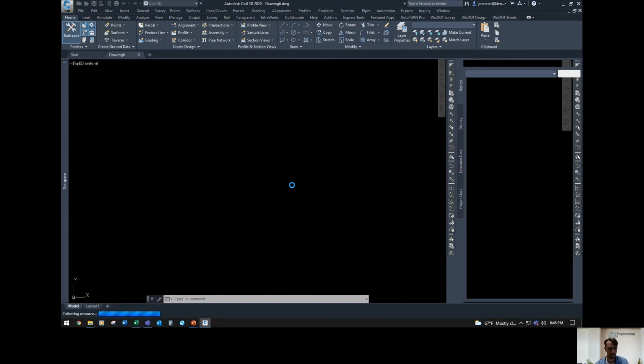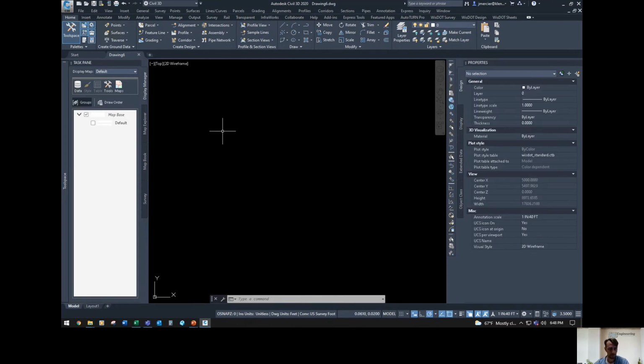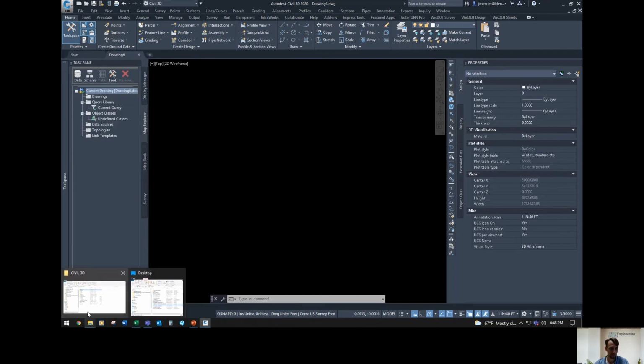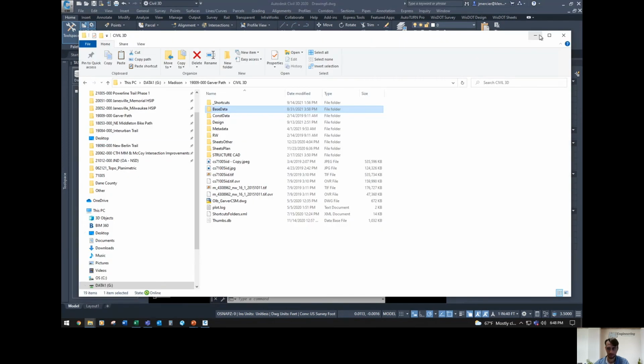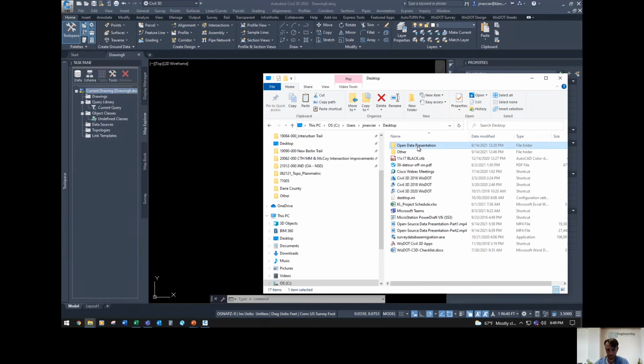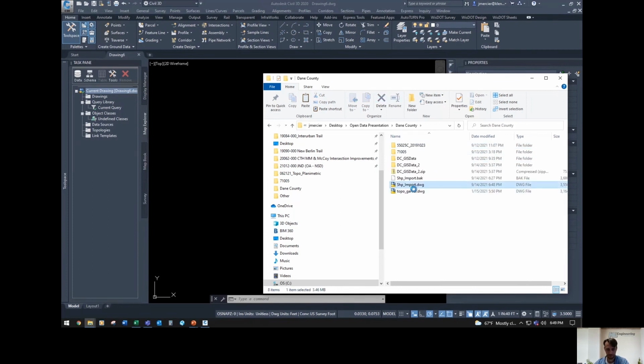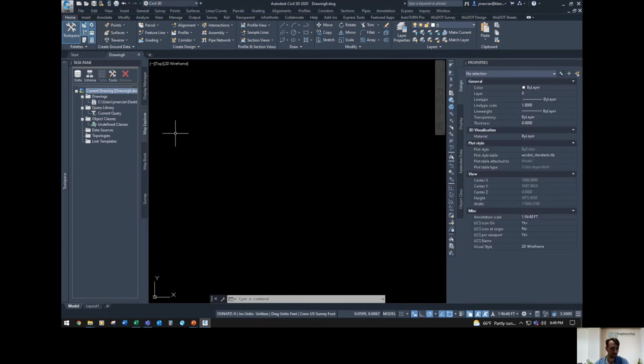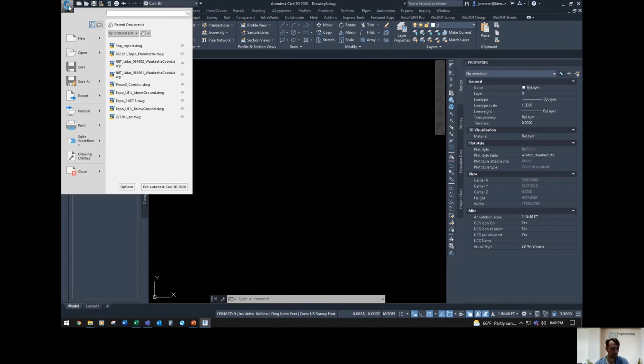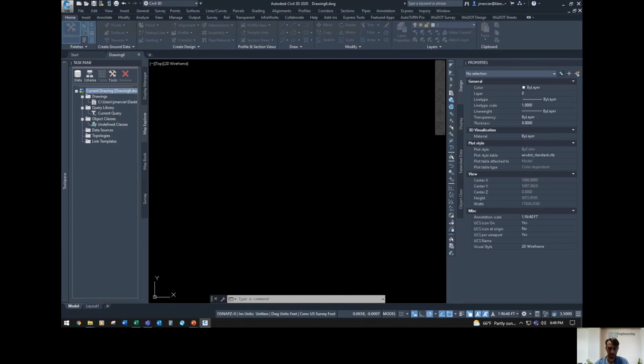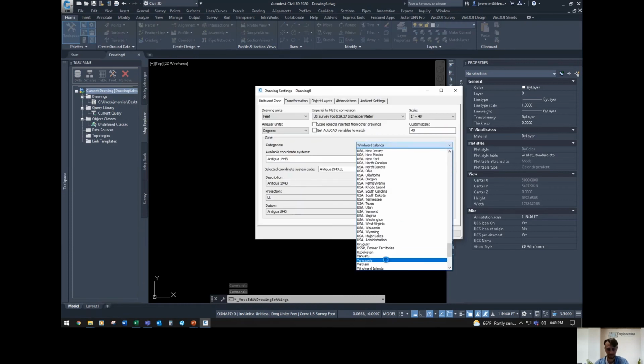The one thing I will say is that we're going to be in the Map Workspace task pane again, and we'll go through how we're going to use that in order to get our polylines in here with elevation data associated with them. So instead of being in the display manager tab, we'll go into the map explorer tab. And what we'll want to do is we're going to drag and drop our file into here. So this is the file that we just imported the shape file into. Drag and drop into drawings here. So now it's connected to this drawing. Before we do anything else, I'm going to make sure that our drawing settings, our coordinate system is set up correctly.